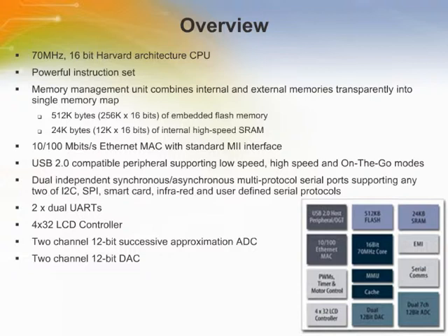The devices are highly configurable with options including combinations of USB 2.0 on-the-go interface, 10 and 100 megabit per second Ethernet MAC, and 12-bit analog I/O. Each variant is available with 512 kilobytes of flash and 24 kilobytes of SRAM.